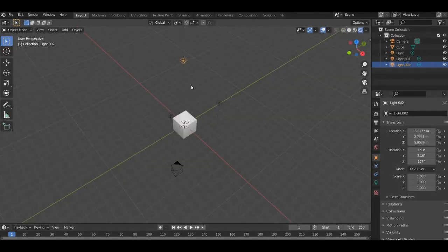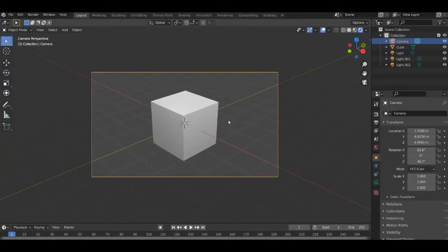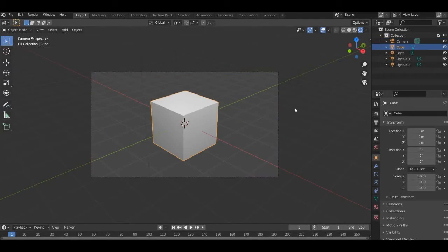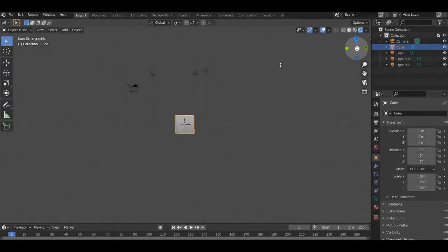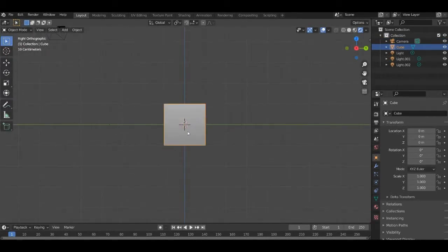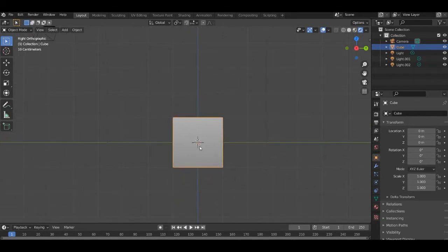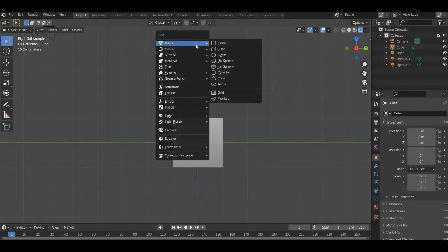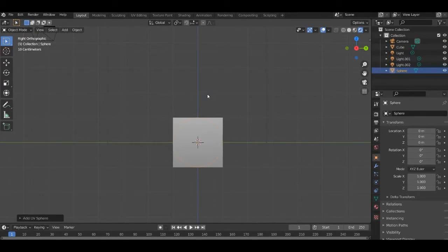So in this one there are three lights, and we want to change the lighting of each, or the power, and maybe the color if you like the idea. So with the camera it's all automatically perfectly on it, but I'm going to add a few things in, so it's slightly harder to create, and it's different from the normal block. So I'm just going to Shift A and add a mesh. I'm going to add an icosphere, G Z, move up.